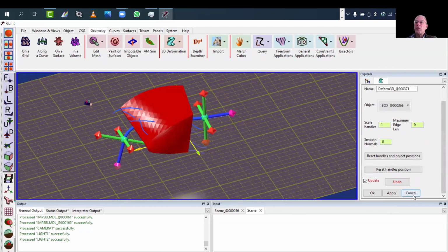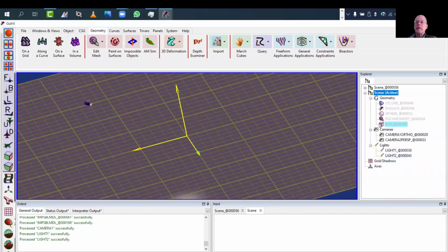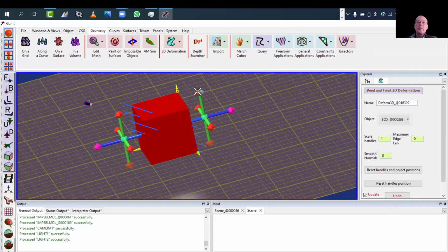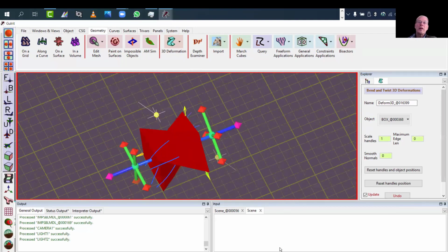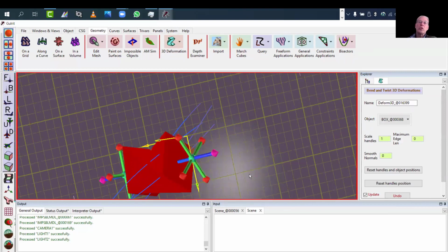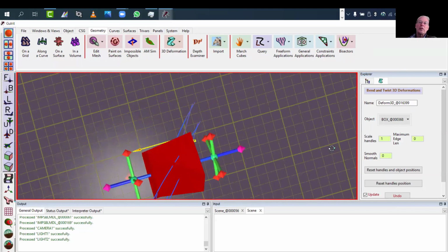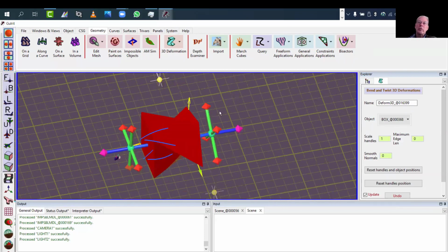And let me start all over with no refinement, because when it's refined, so we're going to select the box again. And if I do the same transformation again, you see that the box is like one solid shape, because there are only 6 faces and 6 polygons, and in fact the polygons are not even planar. It's kind of really weird. They have to be 2 triangles, so you see the entire division there on the silhouette side, but this is really not what you wanted to see in a nonlinear deformation.